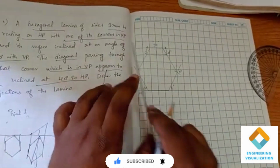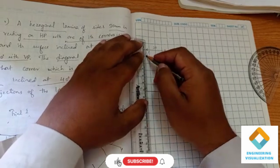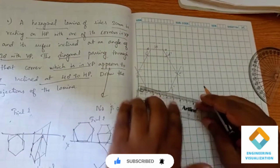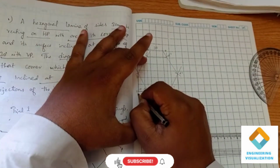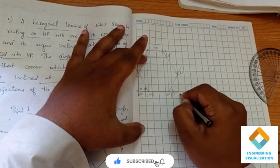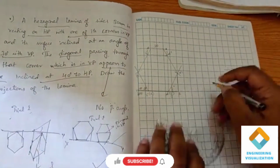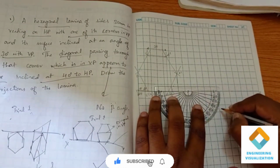So the top we get here on this line, on the XY line. So this is B, C, F, A, D, E, right? For the second angle of inclination, that is inclination to VP, they have mentioned 30 degrees. First I will mark a reference point here, and to this reference point we take an angle of 30 degrees.